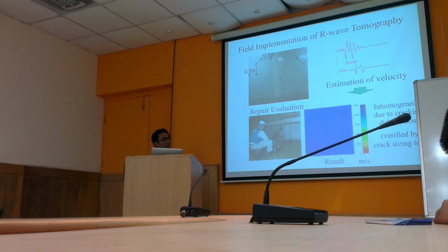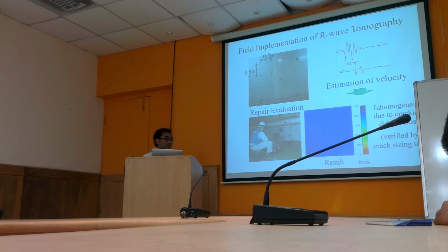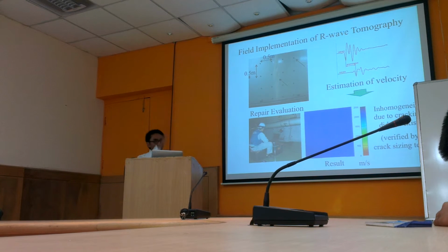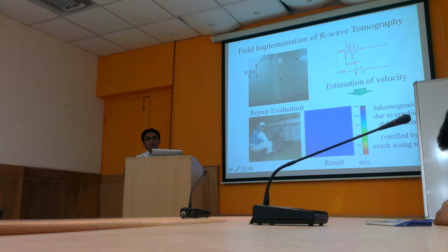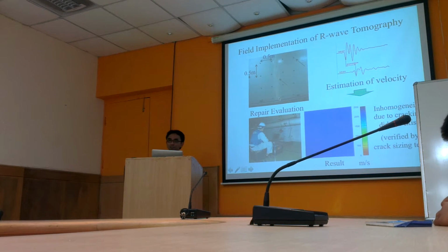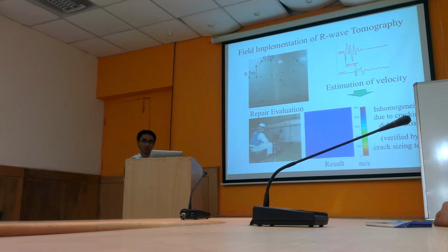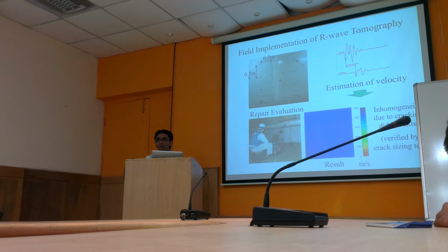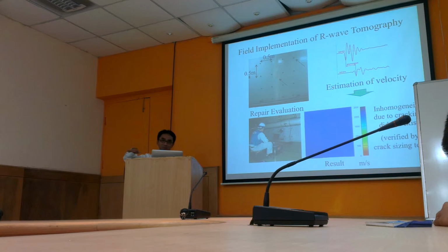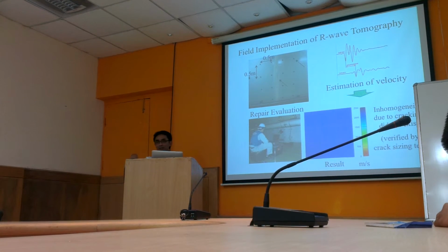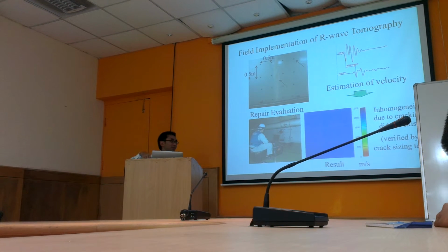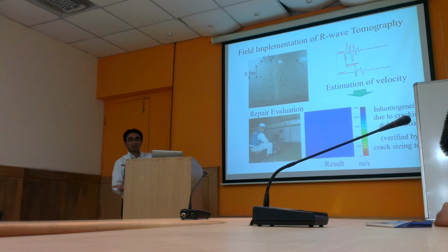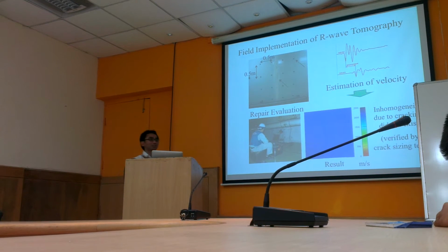So this is another site project. It's actually a nuclear facility in Japan. They found a crack there, this crack, and they have repaired it, but they do not know how effective the repair work is. So they asked us to check. Because sometimes the injection of the epoxy or the grout can stop somewhere in the middle, so you are not actually repairing the whole crack. The injection is not sufficient, so it might leave you with a void inside, but nobody can tell whether there is any void.